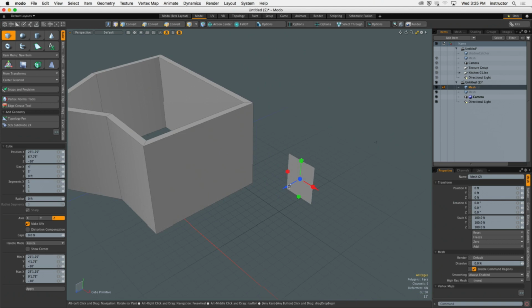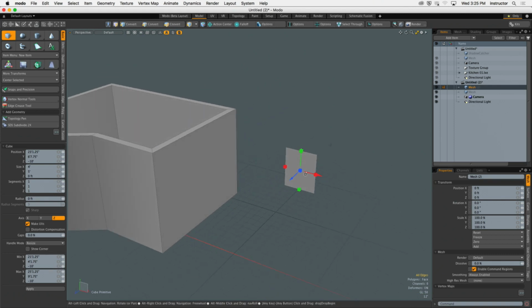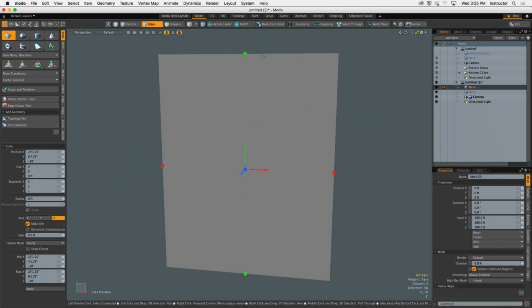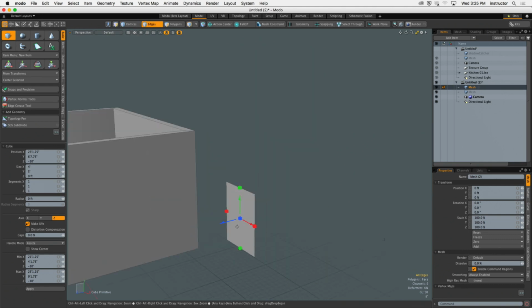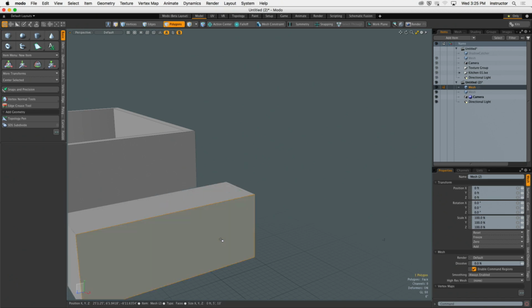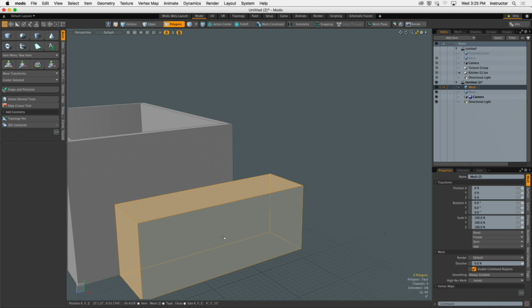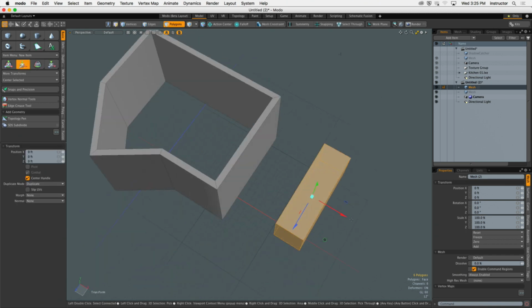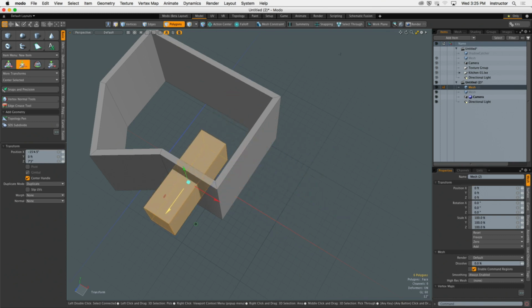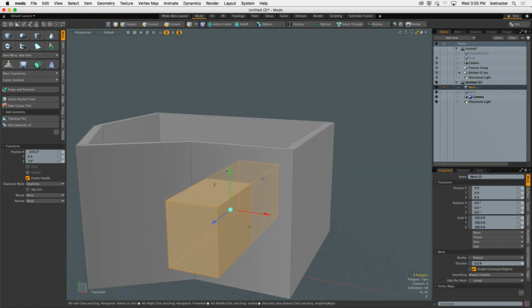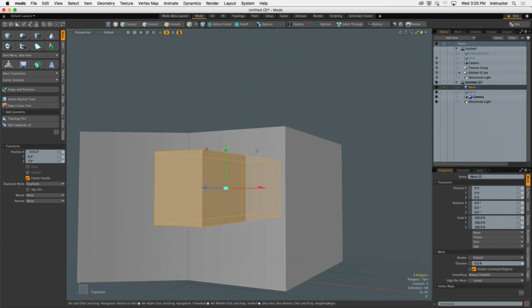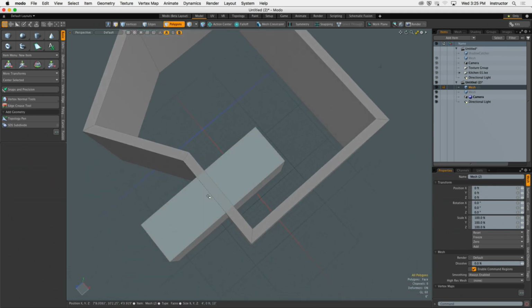Now, all I really care about initially is the dimensions of my window along the X and the Y. These are the dimensions I'm most concerned about. We do need to make it a 3-dimensional shape, but the size of our window along the Z-axis is arbitrary. All we need to create here is a cookie cutter that's going to extend through our walls like this. This is the part that a lot of folks miss. It's got to go all the way through our walls. That way, when we tell the computer to use our cookie cutter to slice our mesh, it slices the outside wall and the inside wall simultaneously. And we know that they're going to be in perfect location to each other.